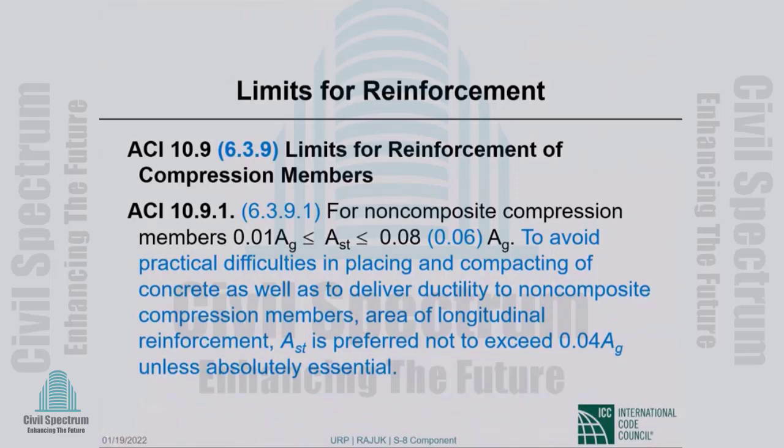The minimum and the maximum. Okay. And this I find very interesting. So minimum 1% I discussed already. It's actually 0.5%. Now 8% maximum. High seismic, it goes down to 6%. Now, 8% reinforcement, if you ask me, it counts the laps.